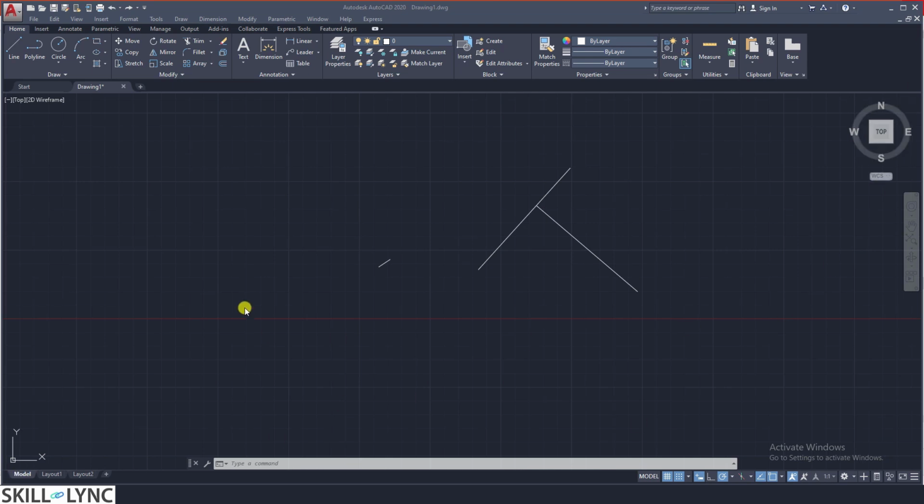Sometimes if you don't specify the limits, the drawing will go outside the boundary areas and it will be difficult for you to bring that into your drawing space. We'll look in more detail at layout space and model space later, but just let us now enable the limit controls by typing in limits.